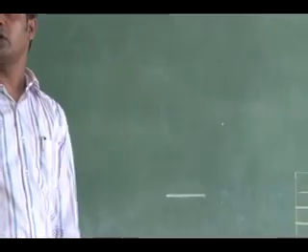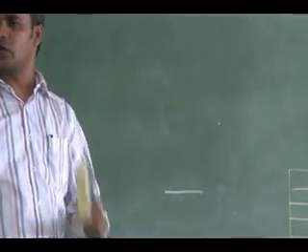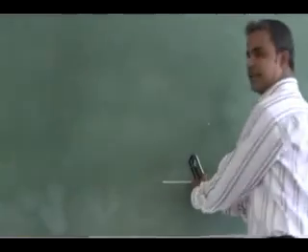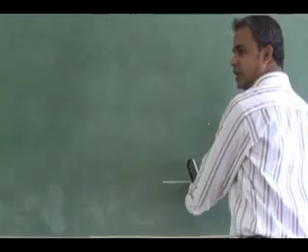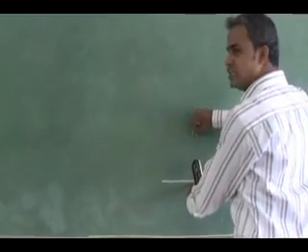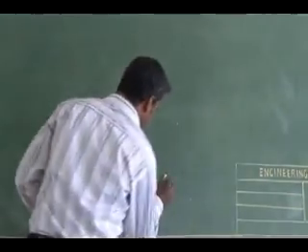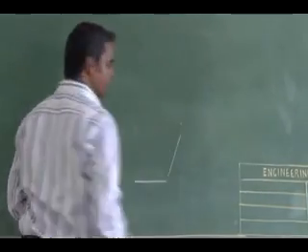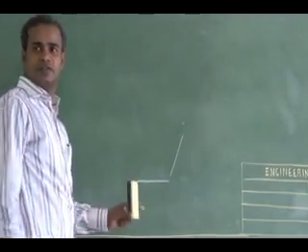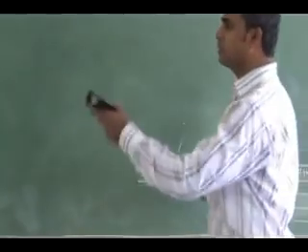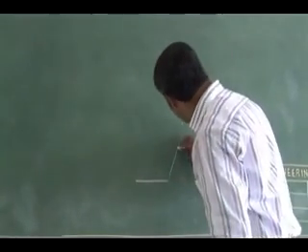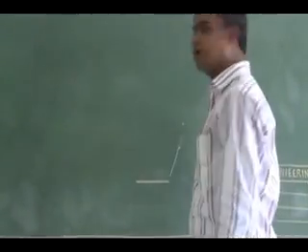How can I construct a pentagon? With 72 degrees or 18 degrees. Easily, I can fix my drafter to this end. The vertical scale of the drafter I can tilt to 18 degrees to the left so that I can get a 72 degree inclination like this. On the drafter itself, I can mark the 20 mm side.